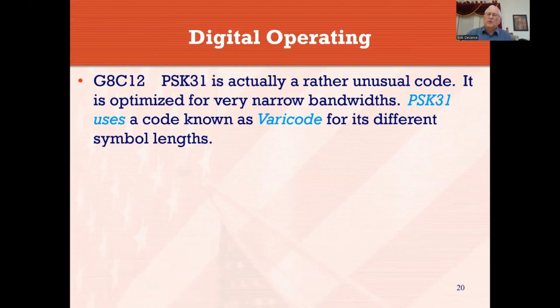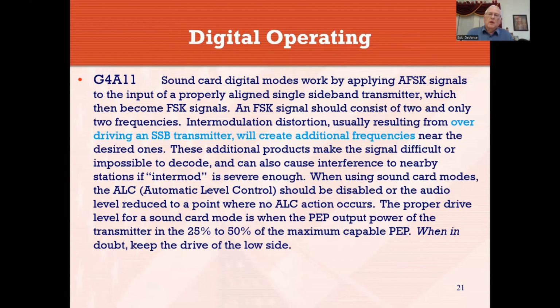The letter E will take fewer characters to send than the letter Z, for example. Varicode. Sound card digital modes apply the audio frequency shift key signal to a properly aligned single sideband transmitter, which then becomes frequency shift key. The signal consists of two and only two frequencies, those frequencies we talked about before, separated by 170 hertz.